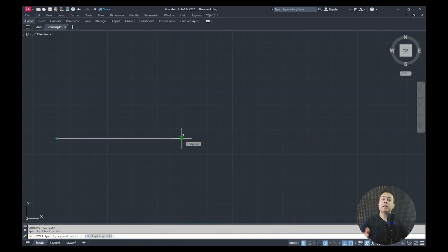The explanation is that in AutoCAD, to measure with DI, you have to press the distance command. In a future video, about dimensions, we'll talk about measurement. Well, I'm measuring this. As you can see, it's still the same, so there's no resizing and no conversion. This is exactly where we say that you don't need to set the unit in AutoCAD. You can choose a unit in your mind and draw your drawings accordingly. Setting the unit is usually for when you want to output from AutoCAD.